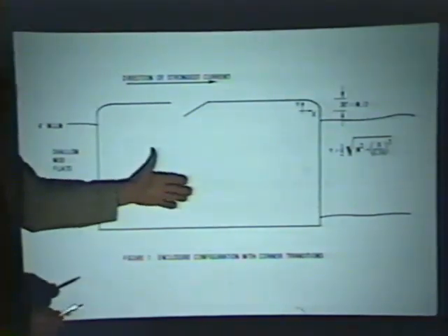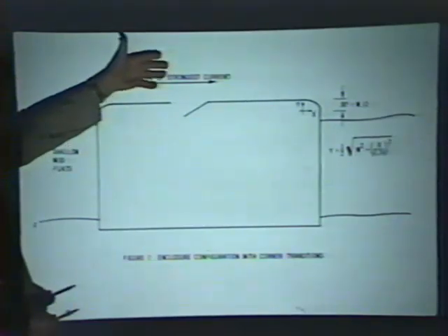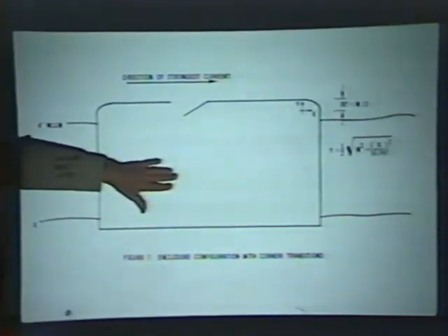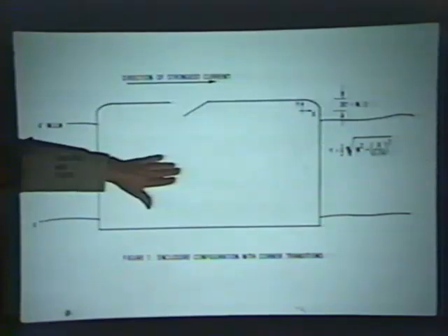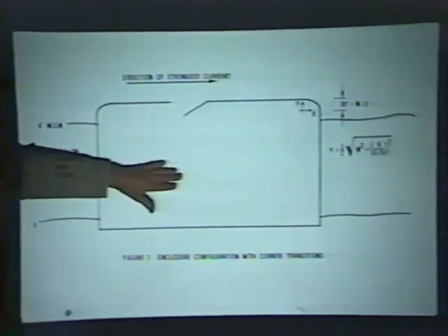We usually do a residence time computation, either model it physically or, in recent years, mathematically, to determine the residence times in the corners and determine whether there's going to be an algae problem. We have a little model that describes algae growth, maximum algae growth rates.